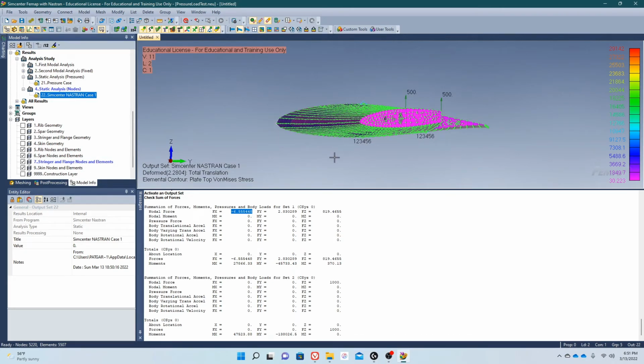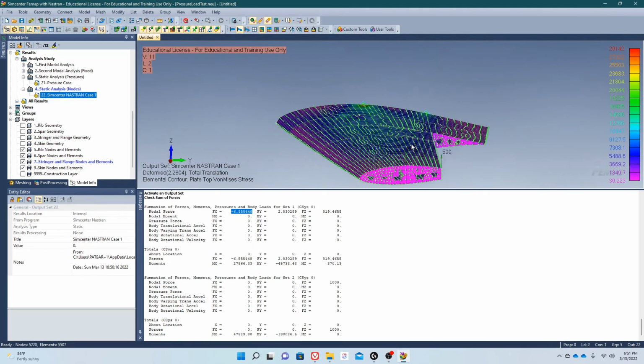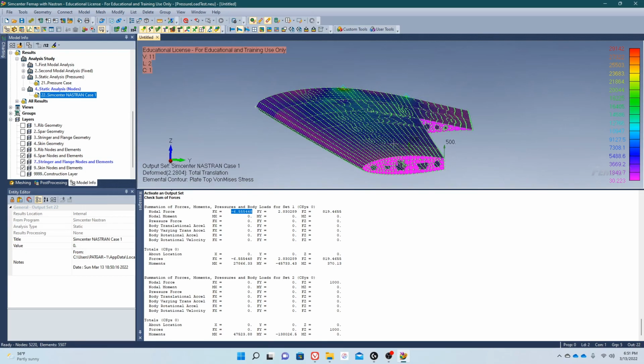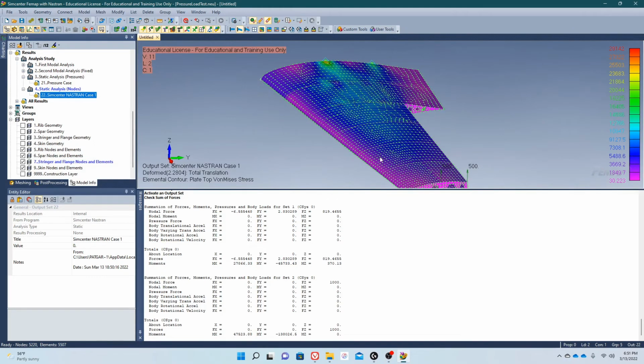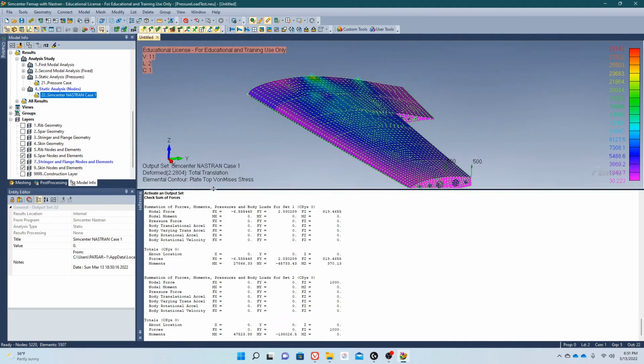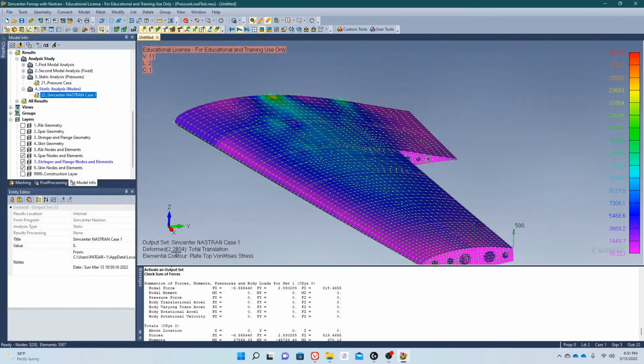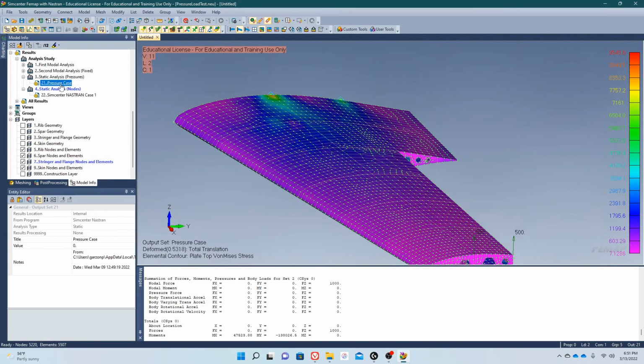And in our pressure forces, these arise from the fact that our surfaces aren't completely flat here at the bottom. So when we put normal pressure loads with respect to the elements or the surfaces, they will not be perfectly in the Z direction. And this, of course, creates differences in moments, which causes differences in your stress formation. So even though we have different displacements, as you can tell in the bottom left corner between both cases, we do get similar results.